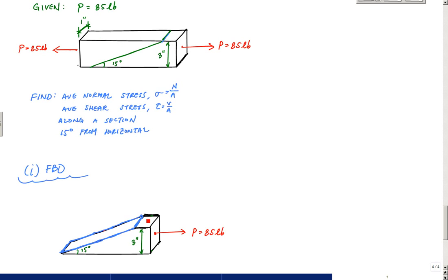But whatever. The other thing that's really important is that when you make that cut, you have to write out what the internal loads are on the inside of the member after you cut it. In this case, I have a normal force on the inside, which I will draw perpendicular. I'll assume that it's positive, causing tension on this face, on this blue area, the plane of the cut. Then I'm going to have a shear force, and I'm also going to assume that it's moving to the right, upwards, if you will, in the upward sense.